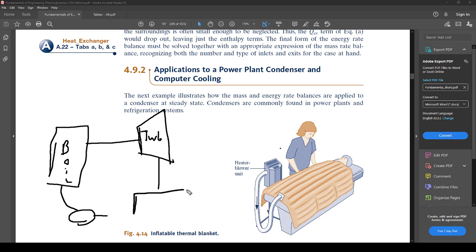Well, we use a condenser. What happens in the condenser is that it runs with lake water. It does a heat exchanger pass with some other fluid, and it removes all of the heat, getting it down to saturated liquid, which is a 100% liquid value. We all know that x equals 0 is saturated liquid on the tables, and it means really liquid. There's no vapor in it at all. And so essentially this right here would be the condenser.